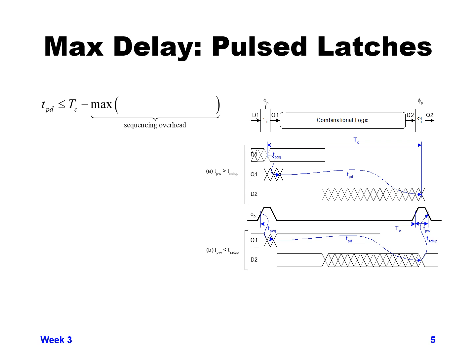Because we need to make sure, again, since these are latches, when we say pulse latches, it just depends on what clock we're sending to them. So the data has to be set up to the closing edge of a latch to make sure that it's stable for a decent amount of time, a setup time, before the closing edge of the latch.